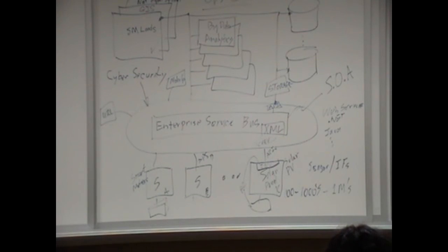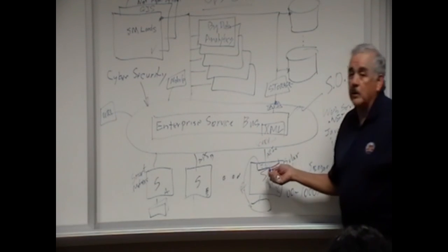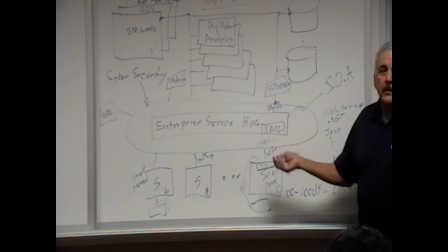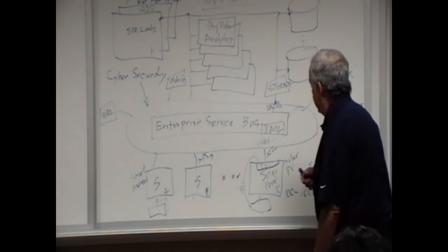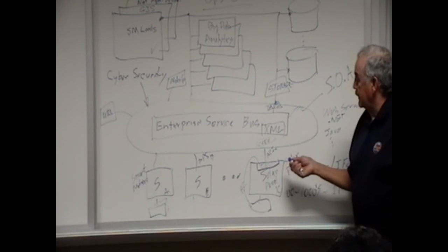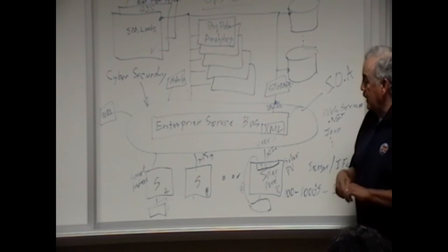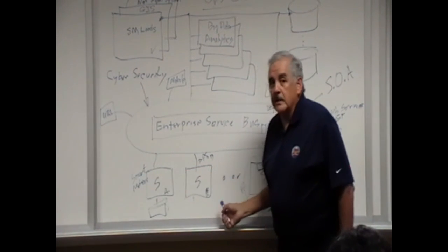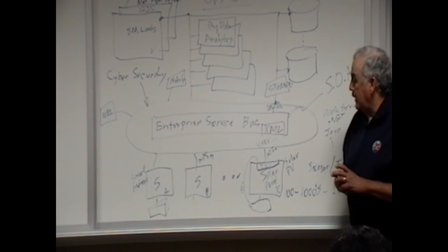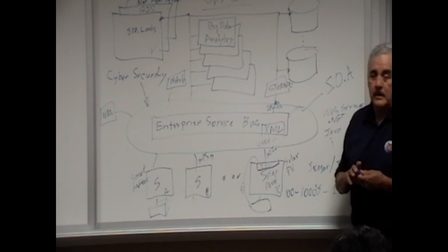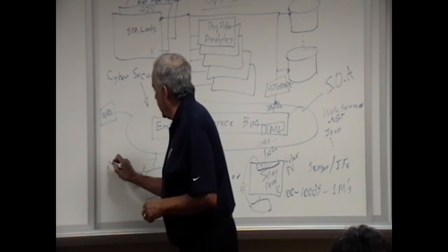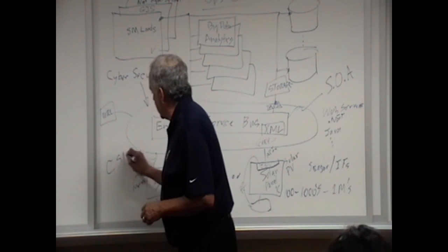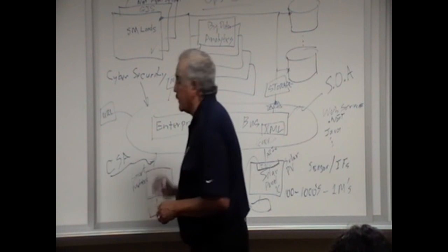You probably don't want that IP address publishable to the internet because somebody will come in there and turn it on, or operate it in a mode that might destroy the inverter. So you have to be cognizant of where there's IP addresses in this equipment and protect those IP addresses, either through the network or through devices that you might put in there, called cyber security appliances, right before it hits the IP address.